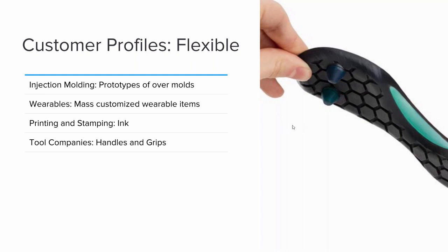This material does not elongate very well, so you don't want to try to stretch it or inflate it. Instead, you want to use it in applications where it's going to be mostly in compression. Also works quite well for vibration dampeners as well. I've done that with it as well.